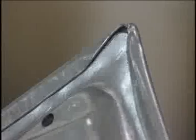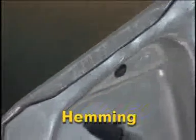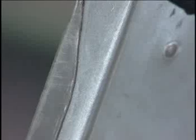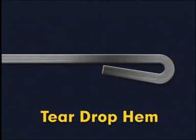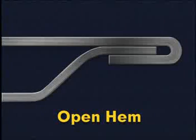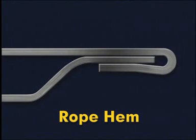In sheet metal forming, hemming is utilized primarily to provide a smooth, rounded finished edge and to attach sheet metal parts together. There are 4 basic types of hems. Those include the flat hem, which can be used with materials having high ductility; the teardrop hem, which is used on materials lacking the ductility required to form the flattened hem without cracking; the open hem; and the rope hem, which are used to join sheet metal parts together.